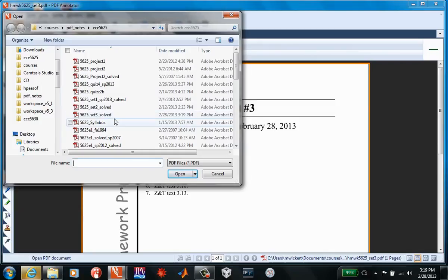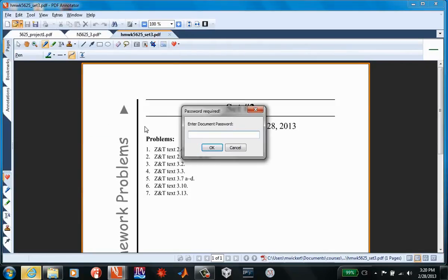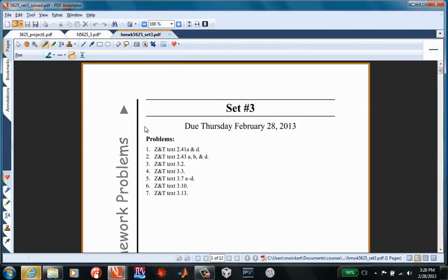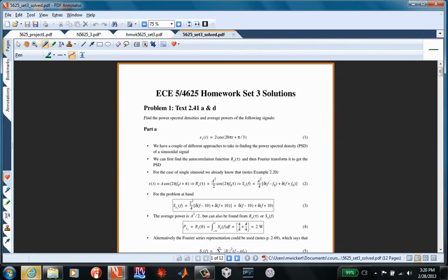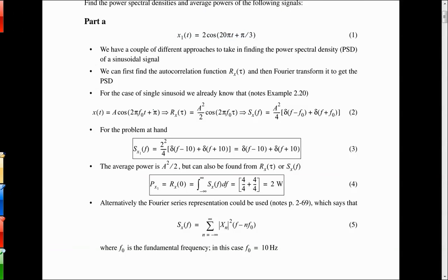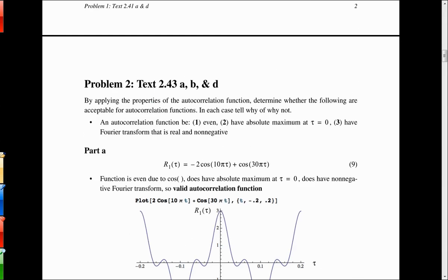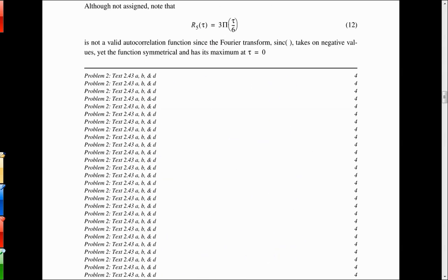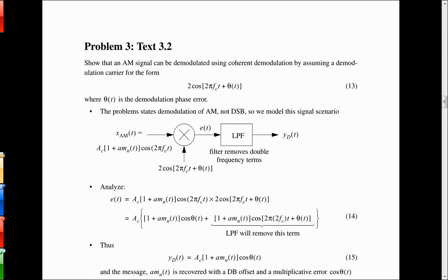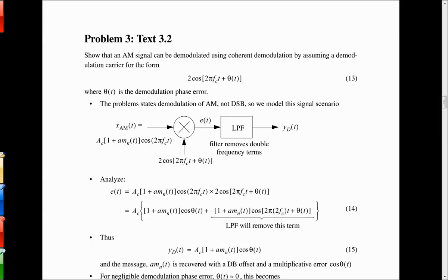Yeah, so I guess my question was, does the phase error there, it's negligible because it corresponds to the coherent? Well, you're not looking at it quite right, but I'll get there. See, this AM signal doesn't have a theta of t in here. If theta of t was here, and suppose this was theta hat of t, those would be coherent.